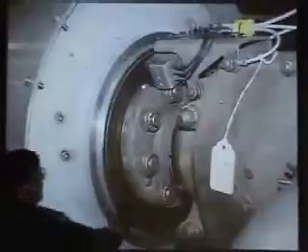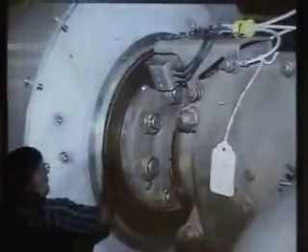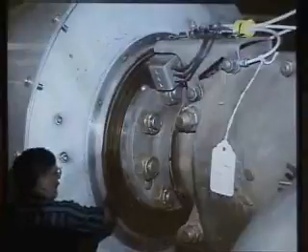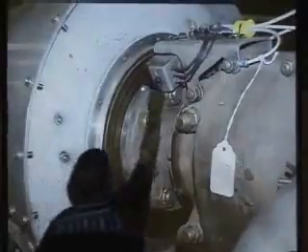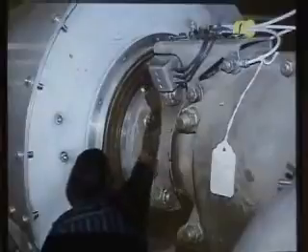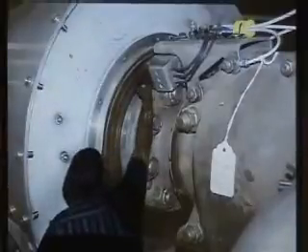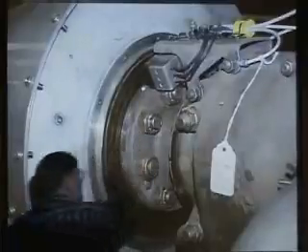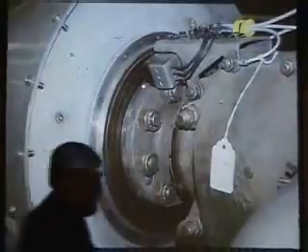And you can see there's 3 rings here. One's going to be ground, one's going to be hot for the inside, and one's going to be hot for the inboard and outboard heating elements. And here's a block. There's only one. This one's busted, but there ought to be 3 carbon blocks or brushes on here, so you would be able to check this during pre-flight as well as looking at the boot for condition.